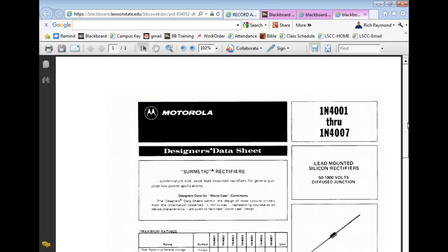Now the reverse breakover, we don't have to do that, because this guy, the 914, by the way, you notice diodes start off with 1N, just about all of them. It indicates it's got 1 junction. Bipolar transistors are usually 2N, because the bipolar transistor has 2 junctions. But of course your FETs are going to be 2N because they're transistors. The transistors were originally bipolar transistors, and the number has no reason; they're basically assigned.